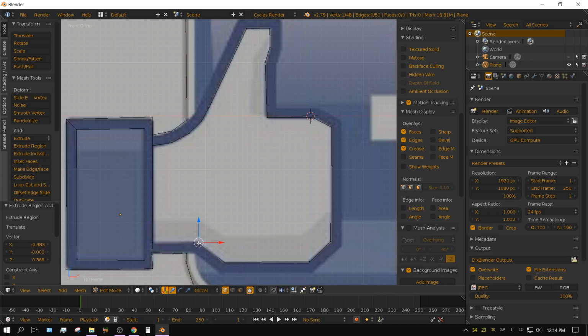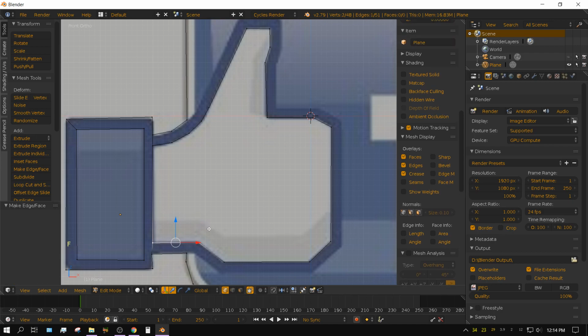And remember, you can't extrude the last piece to this one, you have to fill in the gap. So with this one selected, press shift right click on that one so that both of them are selected, and then press F to fill.